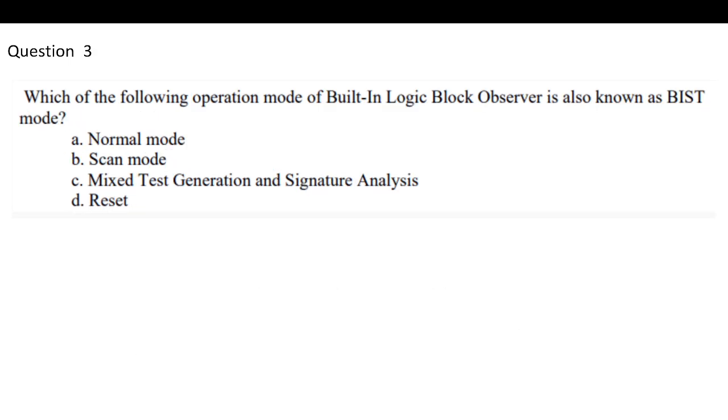Next question. Which of the following operation modes of built-in logic block observer is known as BIST mode? So when we can generate the pattern and compare the response, this mode is called the BIST mode. This is normal scan, and this is when we were able to apply that Y0 directly. The response for that 0, 0.